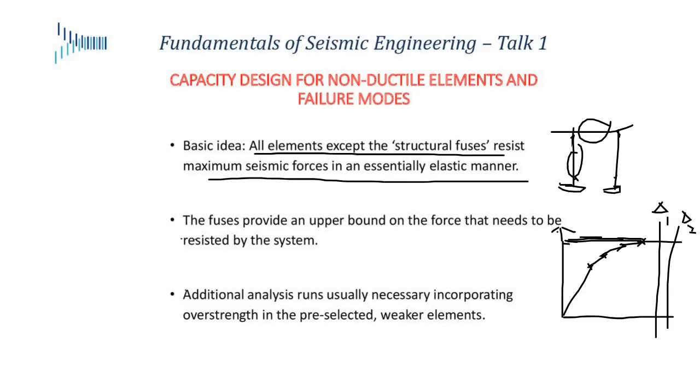The idea is very, very similar with seismic engineering, with structures, because we don't know how big of an earthquake is going to come along. And also, predicting the forces and displacements that are going to happen as a result of an earthquake is, yes, scientific, but it still carries a lot of uncertainty in itself. Okay, so these fuses provide an upper bound on the force that needs to be resisted by the system. That's why they're very important.